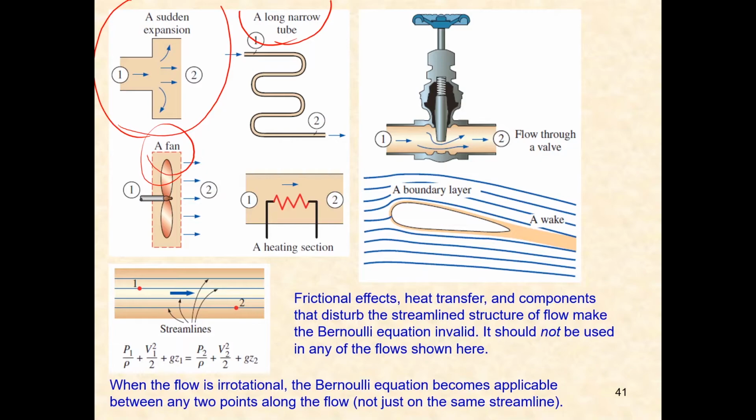It provides more energy or more pressure into the fluid. And when you have heating, it may cause some natural flow to happen. It is also adding thermal energy into the flow, and if you have gas inside, it may cause the flow to expand, so it will become a compressible flow. The example where we have sudden obstructions and then you have a wake. These are all examples where you cannot apply Bernoulli equations.